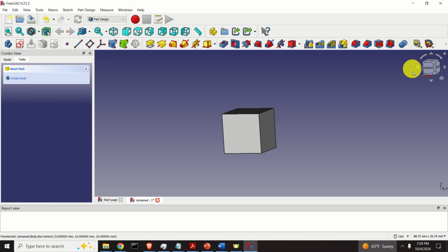Good. Let's start. Double click again on the sketch to return to the sketch, and let's create our rectangle. To create a rectangle, click here. You'll see this drop-down menu and click on Centered Rectangle. Here we will create a rectangle by first specifying the center. Specify the center at the origin, and then you will see how the rectangle is nicely being defined. Just select arbitrary width and height, and later on we will adjust it. So click here, and here it is.